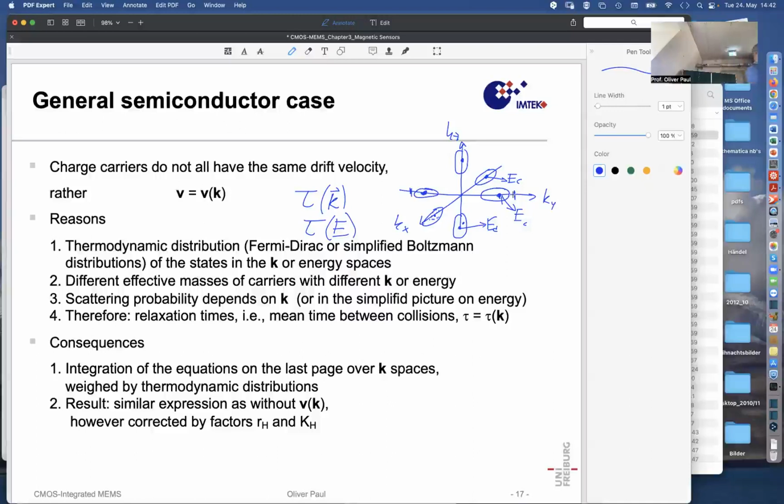You can imagine that an impurity is a charged body. A phosphorus dopant, for instance, has one more nuclear charge than electrons surrounding it. It got rid of one of its electrons, so it's not neutral. And this charged center will influence the motion of a low velocity, low energy electron more strongly than one that can pass by very rapidly, essentially uninhibited.